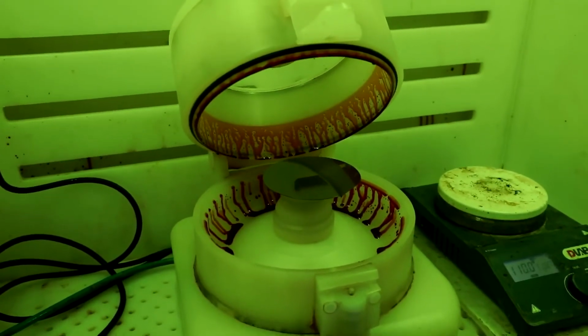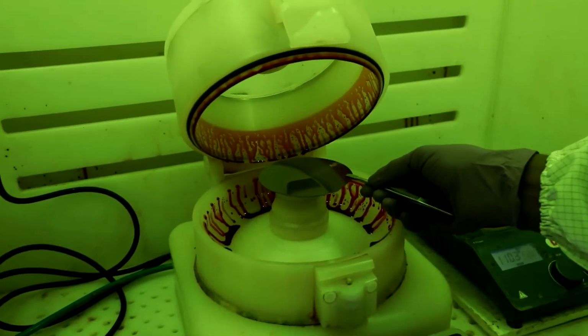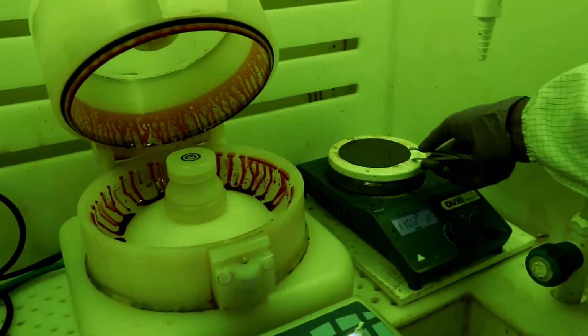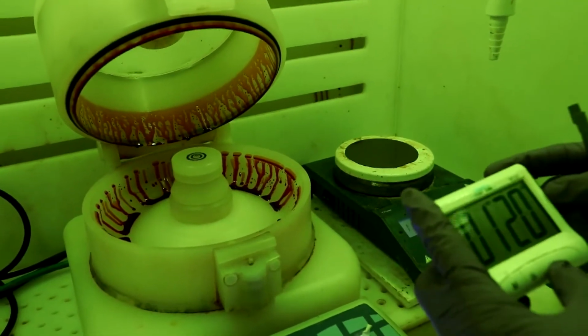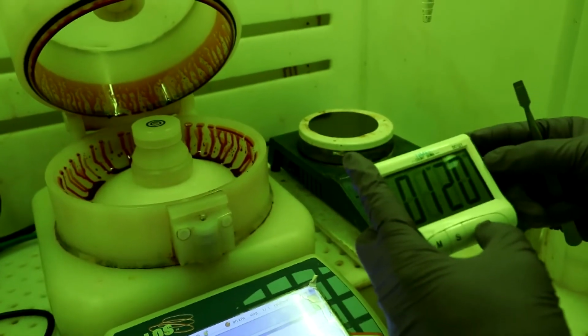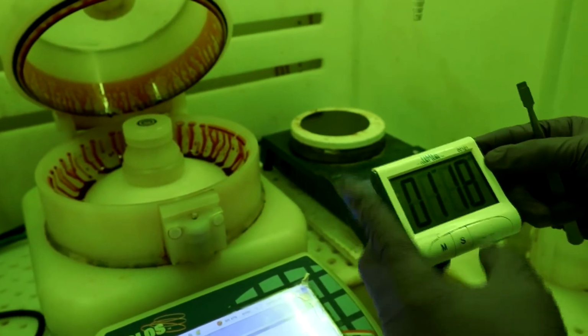Wafer with photoresist layer is then heated to drive off solvents and to solidify the film. Pre-bake or soft bake typically at 80 degrees centigrade to 100 degrees centigrade. It ensures that the substrate does not stick on the photomask plate during exposure.